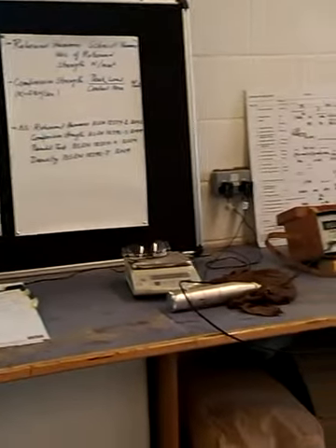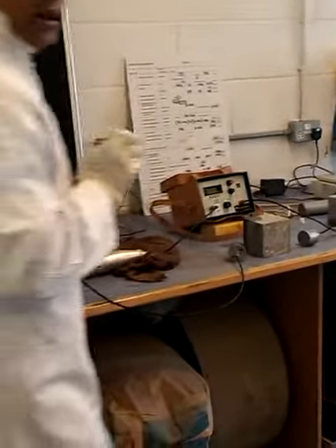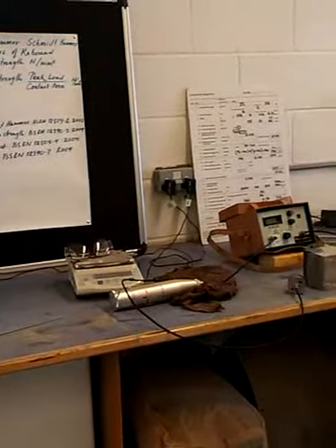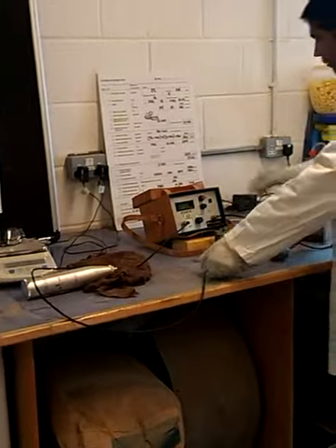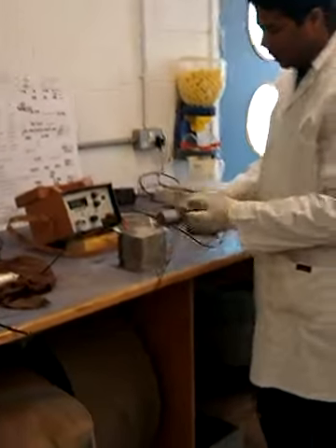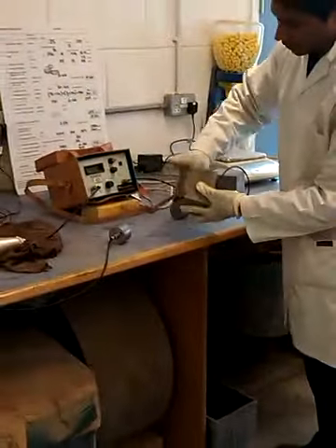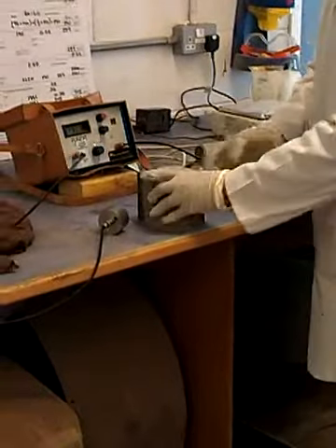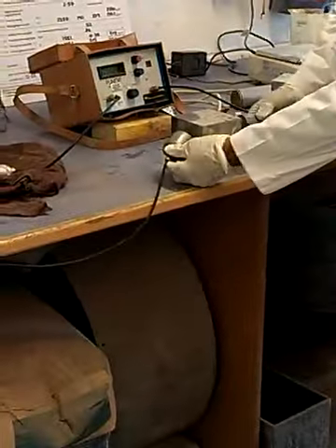Any questions so far for the Pundit test? Any questions? No? Right. So we will see how it can be done. It has already been calibrated. Only for better contact, use the silicone. Now, we're going to take 3 readings, selecting the smooth surface. First, at the center.